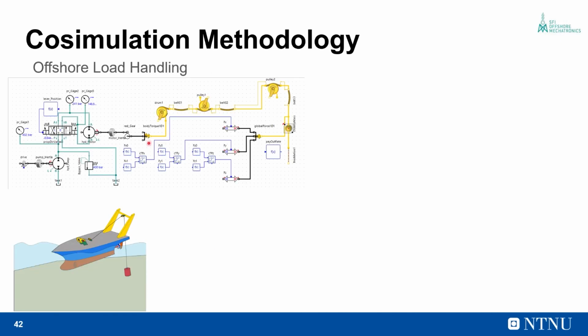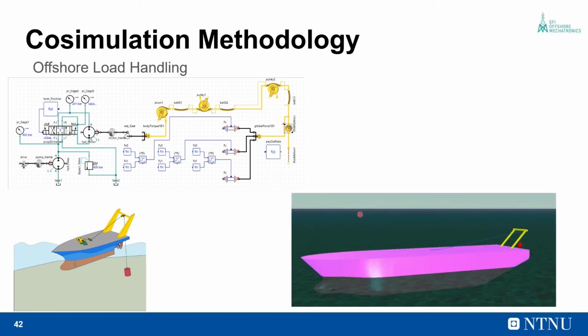This figure shows the electrohydraulic drive of the winch modeled in Simulation X. Simulation X has component models to model the hydraulic motor and the hydraulic valves, as well as the pulley and the belt arrangement for the winch wire. While this figure shows the vessel and the subsea load modeled in Orcaflex, and we couple both these subsystem models using the application programming interface.